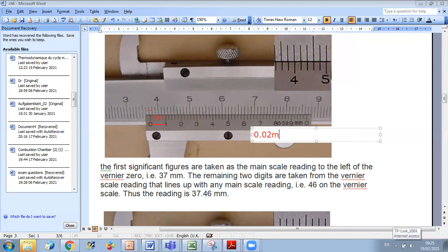In this case you are dividing: the number of divisions you have is 10 times 5, so you are dividing into 50 divisions. So 1 millimeter over 50 will give you that each part can read 0.02 millimeter. This is the degree of accuracy of your scale.